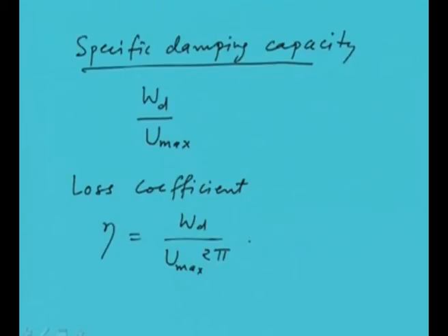Now once we obtain the expression for the loss of energy due to the damping, if we have another form of damping, then on similar lines we can obtain the energy loss. And once we obtain the energy loss, then we can simplify our analysis by a concept which is called equivalent damping system. Let us see how this works.